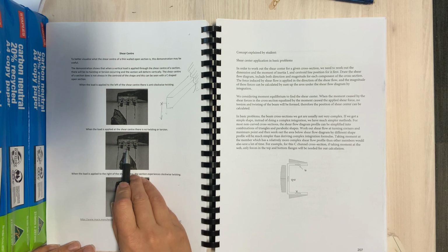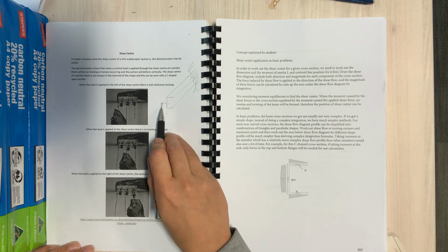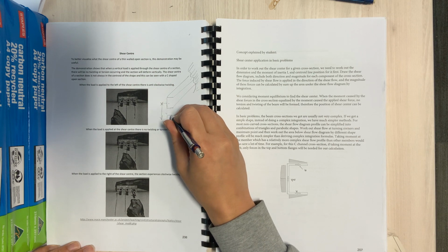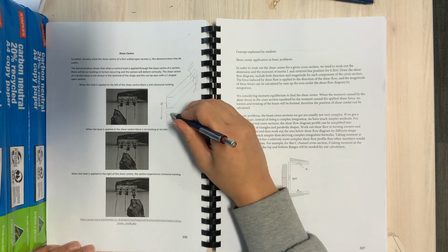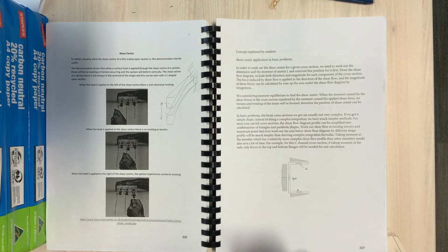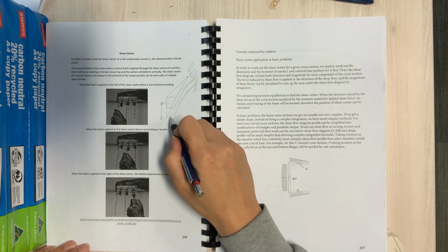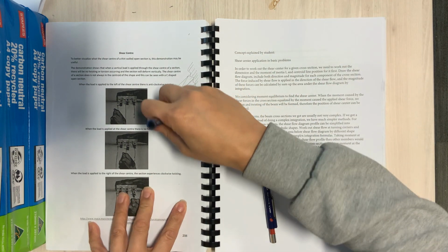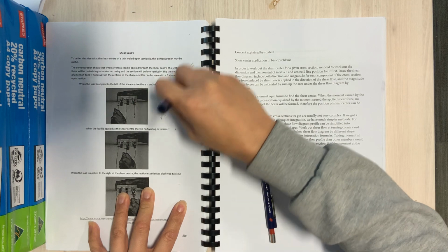Apply the bracket, stick a load down, and you can see that when the load is applied down there, the deformed shape, the whole thing would move downwards. Not drawn terribly well, but you can see the concept. When you pull it downwards at that point, the section doesn't undergo any twisting.